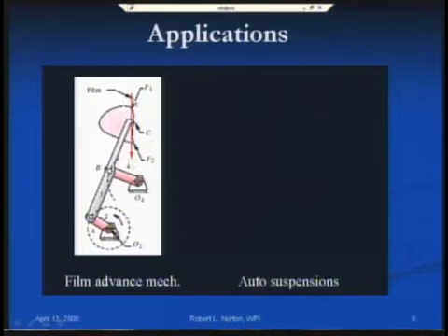It's simply a track, so the film has to go straight. So it isn't necessary for this hook to go in a perfect straight line, and it does not. As I mentioned before, a 4-bar linkage cannot give you a perfect straight line, just an approximate one. But it is close enough for this purpose. But at the bottom, you want to back this hook out of the film without jarring the film, because if you give the film a little bit of a tweak on the way out just as the shutter opens, you're going to see your image on the screen jitter.